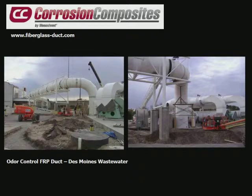So they have to take all of the odor from around the plant, all the different buildings, and bring it into one location. That ductwork is 6-foot diameter, and you see it running about a 90-foot length in that bridge. It's a good example of some of the things that we have to go through. There's an expansion joint every 20 feet in that run.